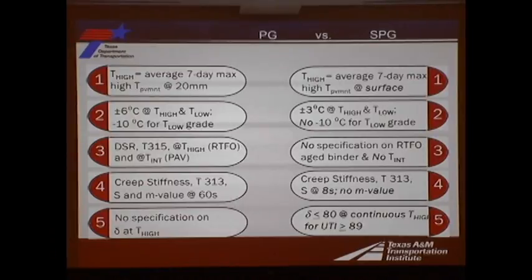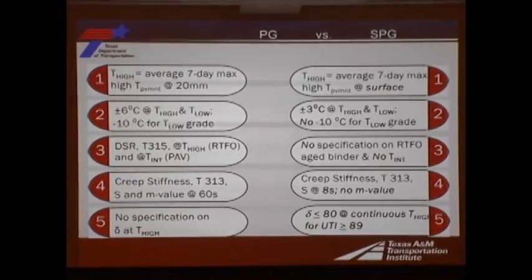We're not doing that for seal coat. We're trying to make a spec that addresses seal coats, so you're concerned about the temperature right at the surface, and you're not concerned about rutting or cracking because seal coat doesn't do anything for those properties. We're concerned about flushing and chip retention. So we're targeting a spec right at seal coats, and that's why it's a little bit different. And the key thing to remember is because we're looking at different parameters, the properties of the materials don't correspond.